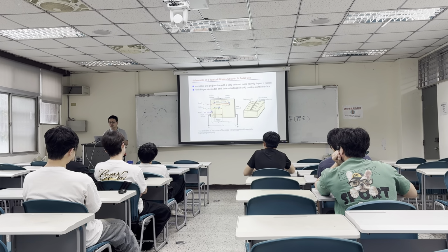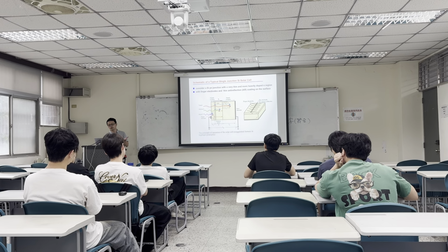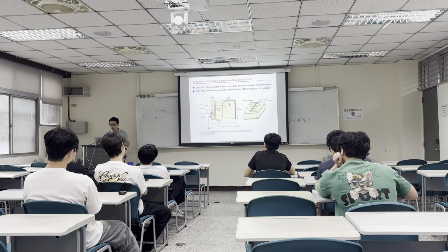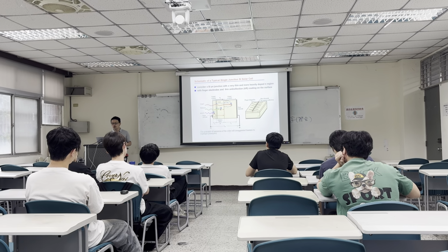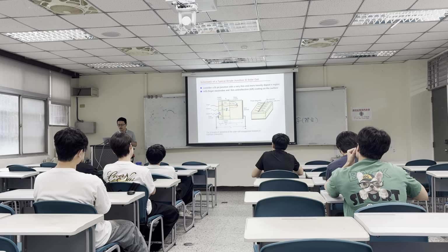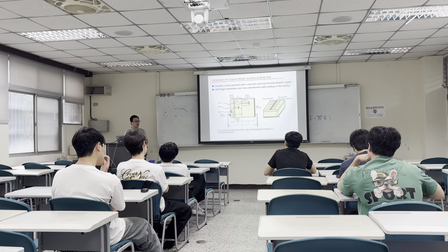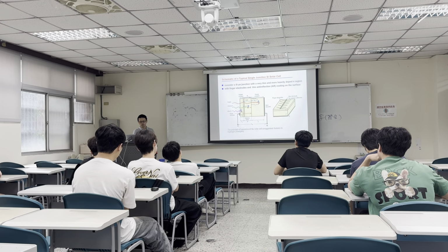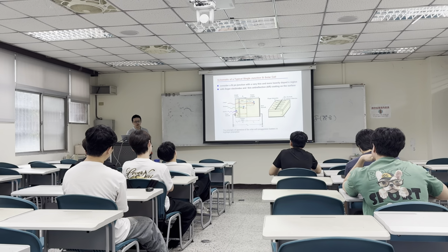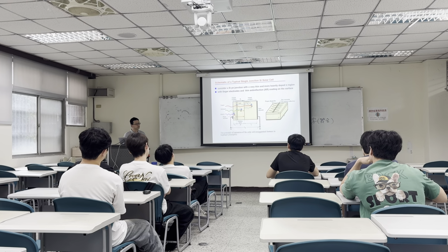So this kind of contact is called a finger electrode, and the other one is called the busbar electrode. So you have the finger electrode and the busbar electrode for the connection of the whole contact area. And at the bottom, you don't have any issue about the light illumination, so you should put the bottom contact to cover the whole substrate.